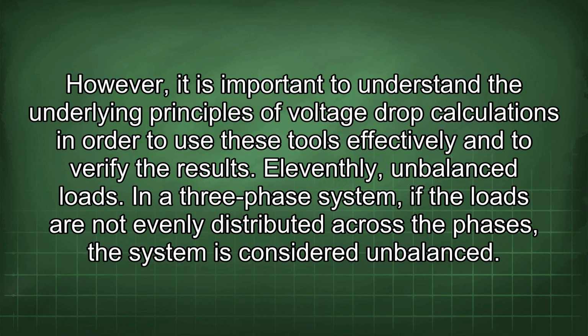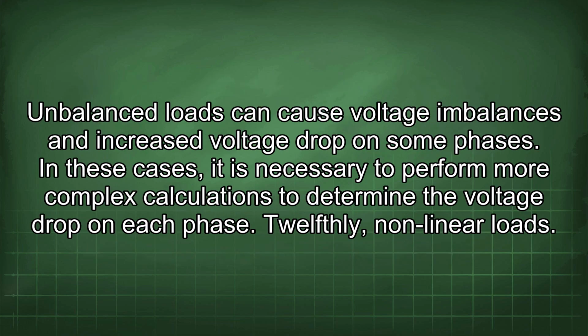11thly, unbalanced loads. In a three-phase system, if the loads are not evenly distributed across the phases, the system is considered imbalanced. Unbalanced loads can cause voltage imbalances and increased voltage drop on some phases. In these cases, it is necessary to perform more complex calculations to determine the voltage drop on each phase.